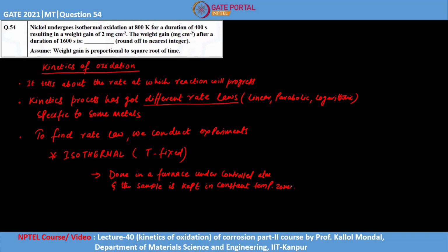Now after putting the sample in a constant temperature zone, we'll measure weight gain per unit area as a function of time, because once we keep this metal in a furnace under controlled atmosphere, it will oxidize and metal oxide will form on the surface,